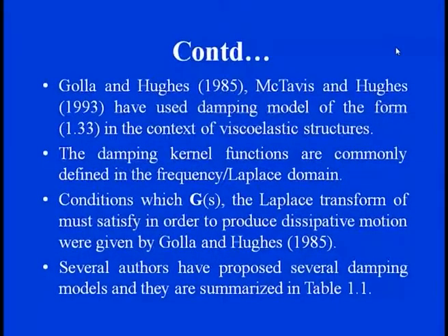So various damping models are available in the context of viscoelastic structures also. And the damping considered through kernel functions is commonly defined in the frequency or Laplacian domain, because in these cases we can clearly interact with the energy formulation. So the conditions in which the kernel function g of s is considered in the Laplace transformation, it has to satisfy whatever the dissipation motion is along with the entire part.